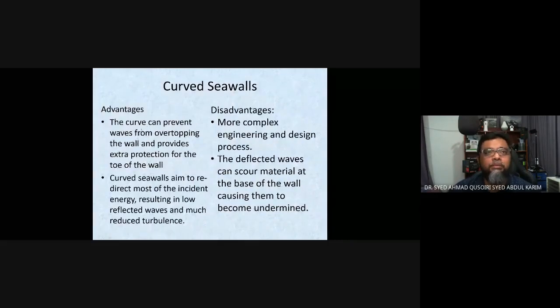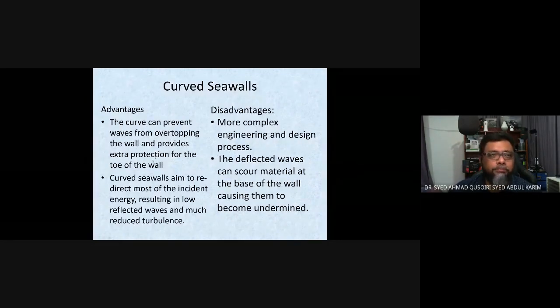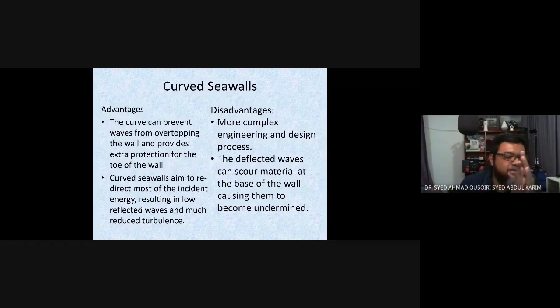Advantages, of course, being mentioned here. The waves can't overtop the wall. It redirects most of the energy. So this will result in a lot less pressure towards the wall itself, because it's curved. It's not just impacting the flat wall. So this type of curved wall will last a lot longer.